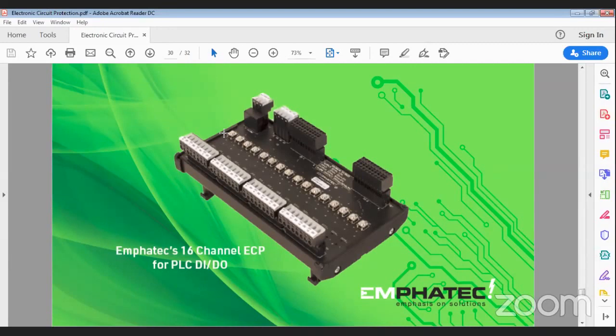Because it's an electronic circuit, you have all that flexibility that you wouldn't on a breaker or fuse. You also have the ability to turn them off remotely. So compared to a shunt trip breaker, the shunt mechanism could add considerably to the cost, where an ECP product could just be a digital input from the PLC or from a push button somewhere and you've turned it off. So they have their advantages. Speed is the main one.